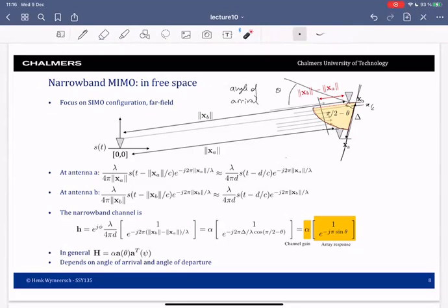All right, so because of this configuration, there's a certain delay difference here, which depends on the distance between the norm of XB and XA. And when the wavefronts arrive, I remember we use plane waves, so the wavefronts will arrive a little bit earlier to antenna A than to antenna B. So the signal arrives earlier here and later here.